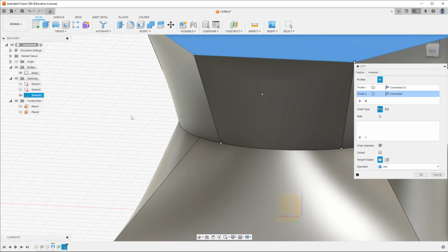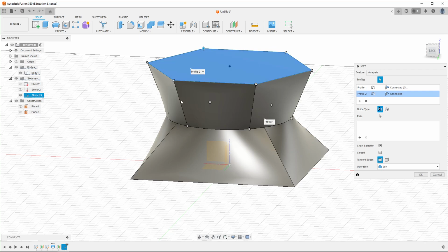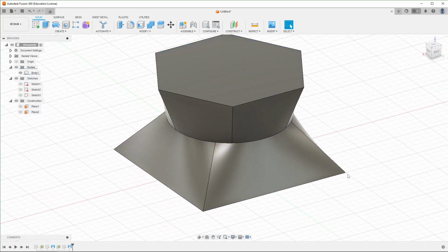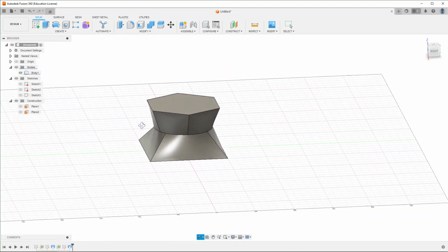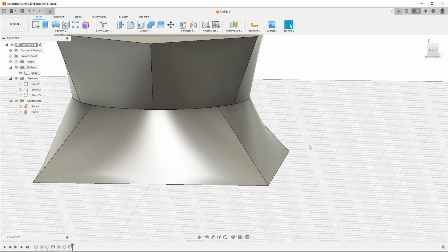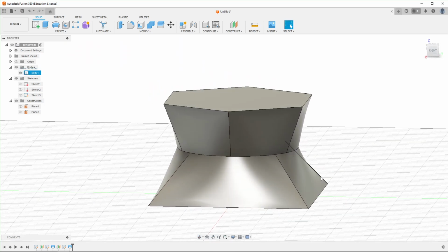And again, it's a little more subtle because there's more sides, so it's almost like a circle going to a circle, but obviously there's only 6 sides here. So there is some curvature as we go through here, right? So there it is. The Loft tool is really great, convenient. Again, I'd say it's not necessarily always common to do from sharp edge to rounded edges, but if you need that or if you want to, that's a pretty convenient thing to do. We can do a lot of interesting stuff with this as we go along.